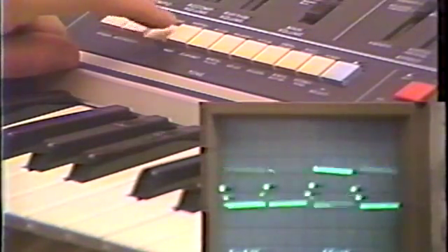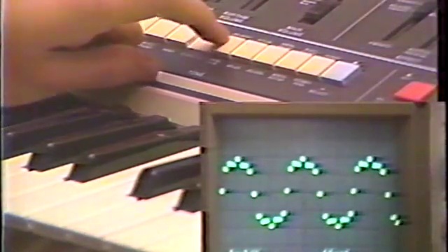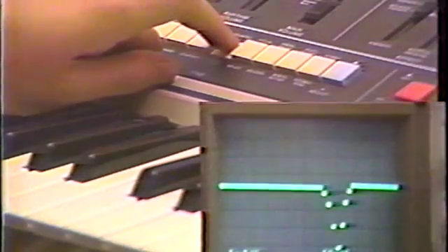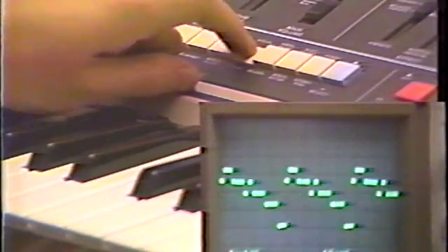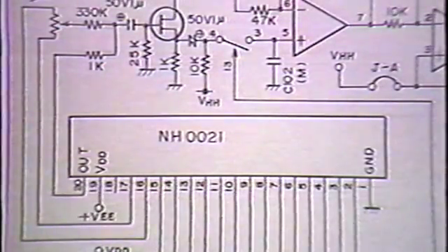The 14 digital signals enter the digital to analog converter, where they are converted to a stepped analog waveform. The shape will vary depending on the voice used. With the CT430, the digital to analog converter consists of just one part. Almost all of the models use a circuit like this for the digital to analog converter. Since the LSI outputs only a small current, an inverter is used to increase the current.